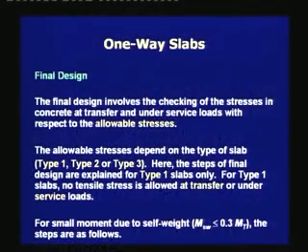Then we are moving on to the final design, where we are checking the stresses in the slab under the service load conditions. The final design involves the checking of the stresses in concrete at transfer and under service loads with respect to the allowable stresses.